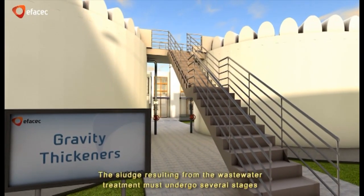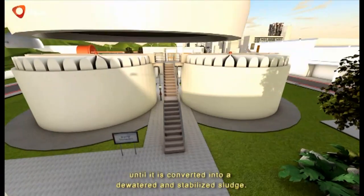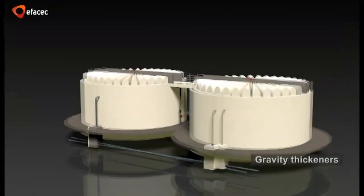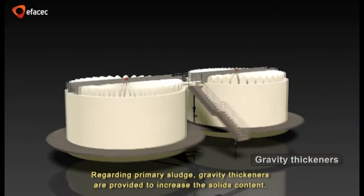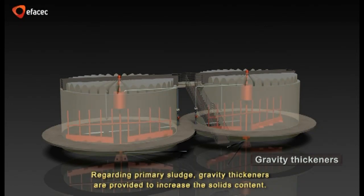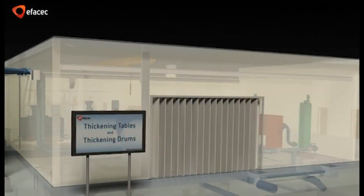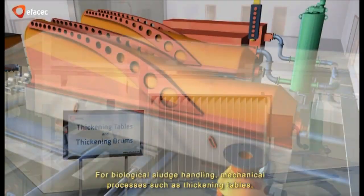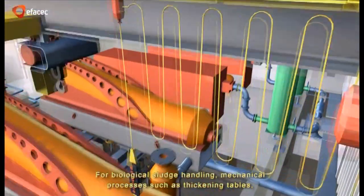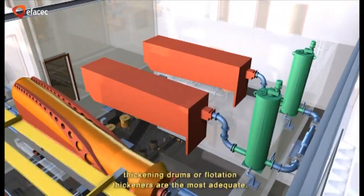The sludge resulting from the wastewater treatment must undergo several stages until it is converted into a dewatered and stabilized sludge. Regarding primary sludge, gravity thickeners are provided to increase the solids content. For biological sludge handling, mechanical processes such as thickening tables, thickening drums, or flotation thickeners are the most adequate.